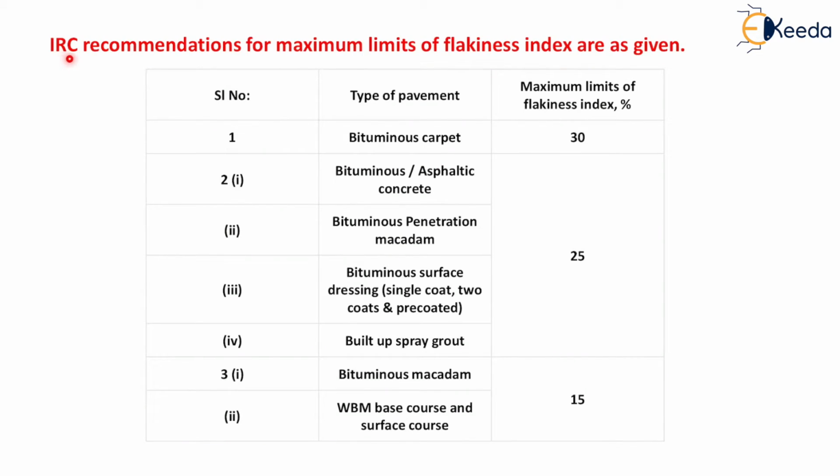Now, the Indian Roads Congress recommendation for maximum limits of flakiness index are as given. For bituminous carpet type pavement, the maximum limit of flakiness index is 30. For bituminous asphaltic concrete, for bituminous penetration macadam, for bituminous surface dressing, and for built up spray grout, the maximum limit of flakiness index is 25. And for bituminous macadam and WBM base course and surface course, the maximum limit of flakiness index is 15.